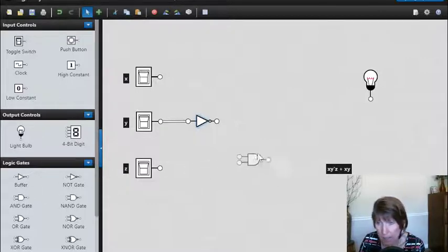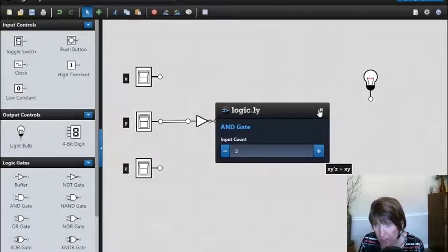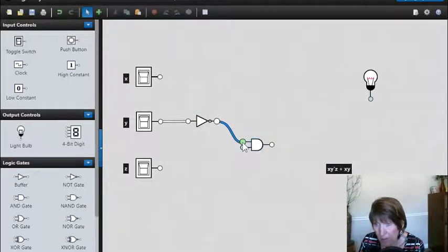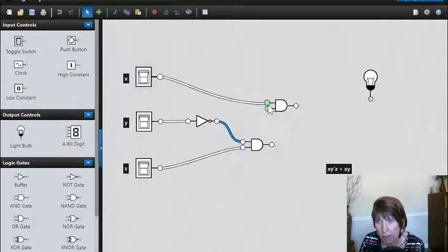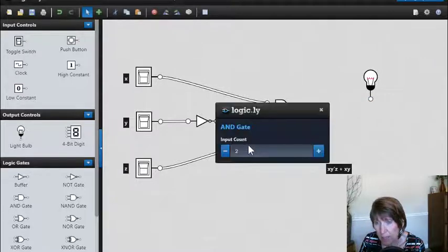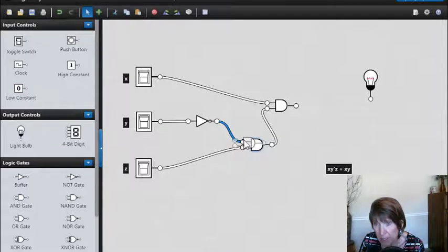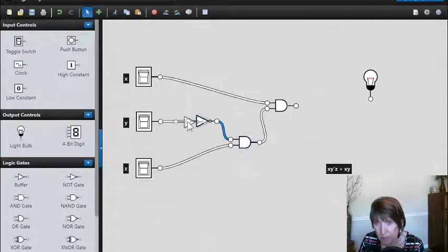Let's say we've got AND gates have only 2 inputs. So we take the input from the Y naught and the Z. So now we've done Y naught times Z. Now we need to get it times X. So it's going to require another AND gate. And there we have that other AND gate. Okay, and so that really gets us the 2, make things a little bit tighter here. So that gives us really just the first term, X times Y naught times Z.